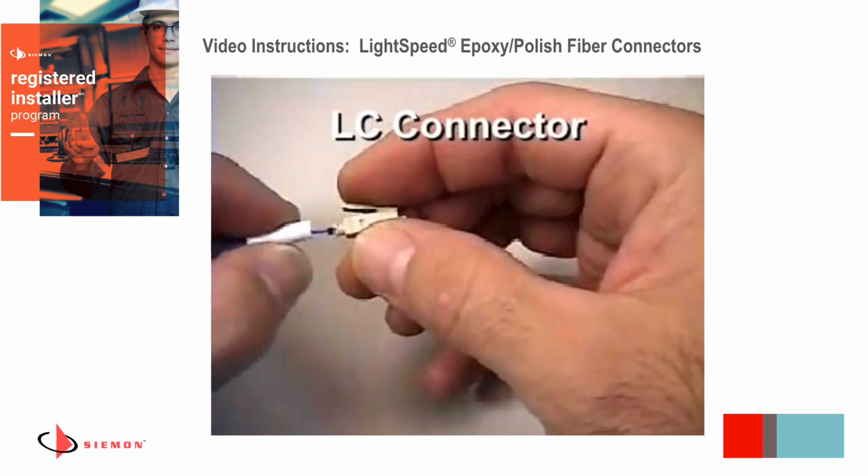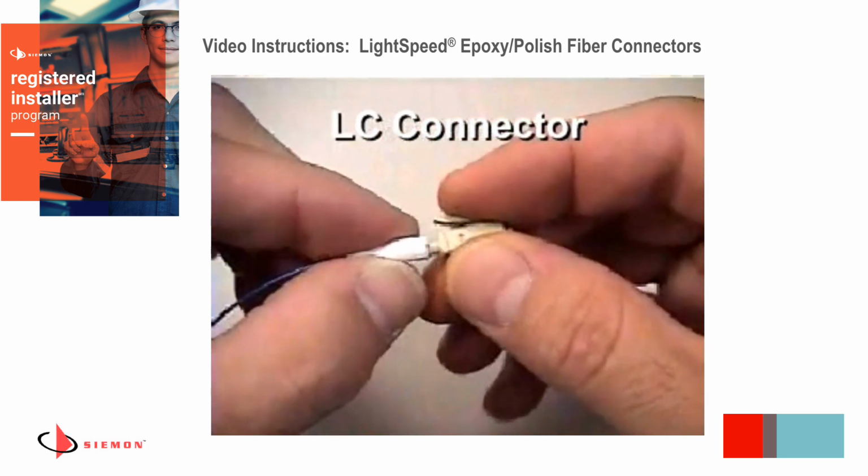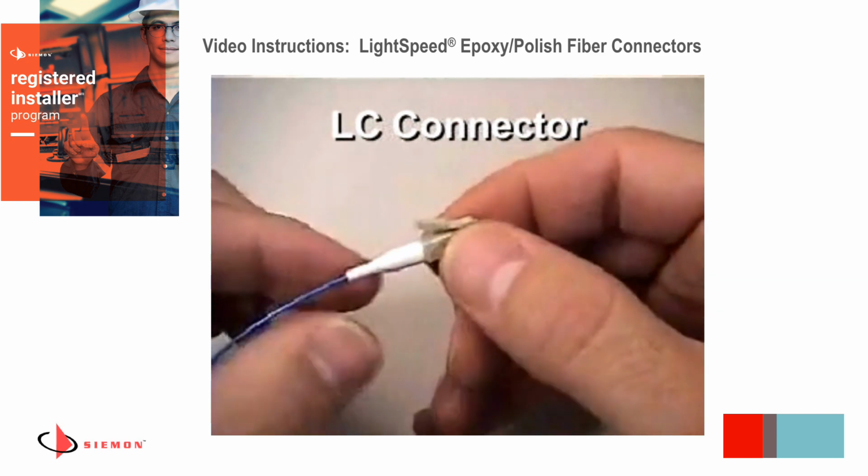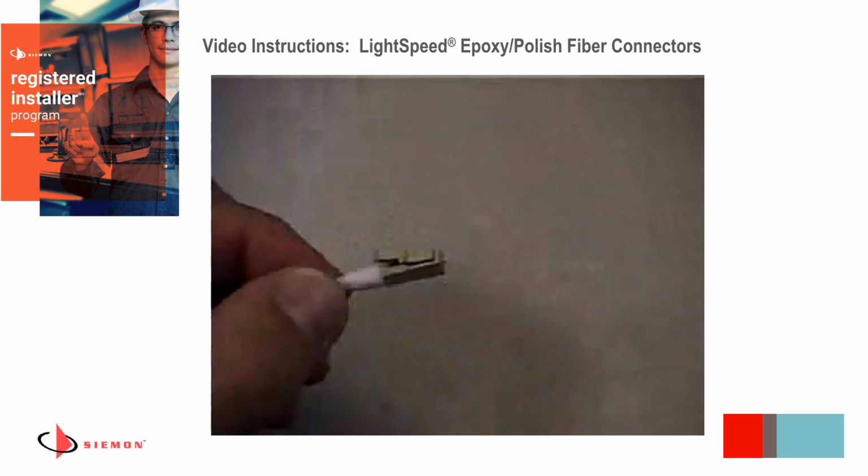Also be careful not to bump or brush the end face of the ferrule tip before polishing. The small fiber nub is still somewhat vulnerable to being fractured.